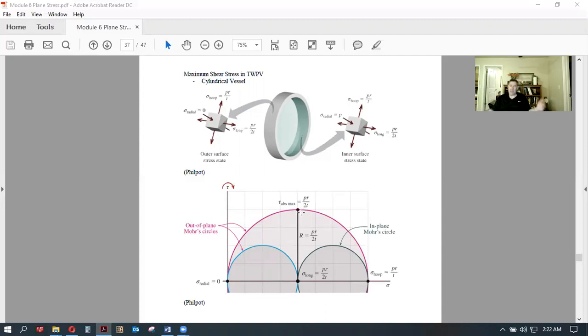Depending on the ratio of shear yield to tensile yield, that can be a pretty important number that's showing up. If you look in the other direction, on this bottom surface, then you'll see the longitudinal stress being the maximum and the radial stress is still zero. So that's this other smaller circle. That's just different sides of the stress cube that we're looking at, that we see in the plane side. And then these other models that show up. So there's three more circles to be looking at.